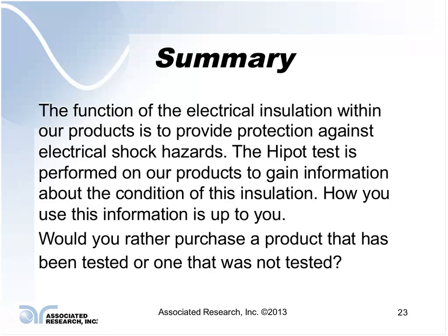If you have your leakage current set slightly too low, you may get a false failure in some cases. If you're doing a DC test, it could be due to charging current. If you're doing an AC test, you may be utilizing arc detection.